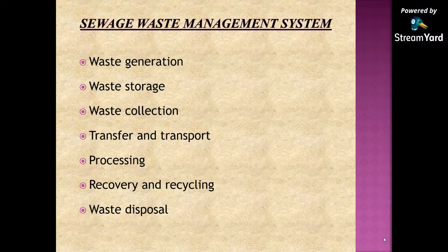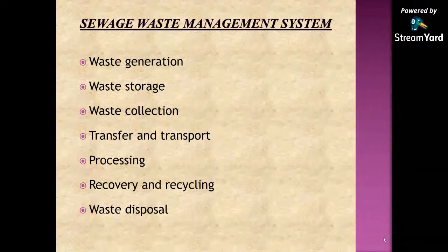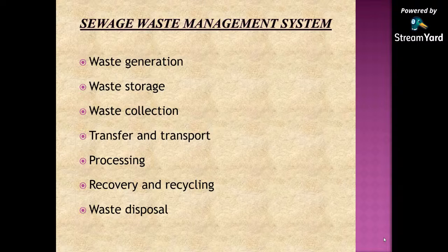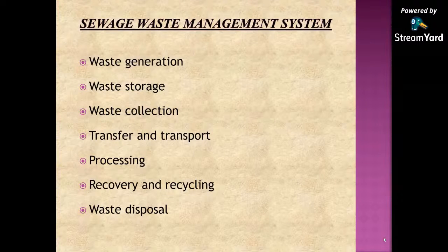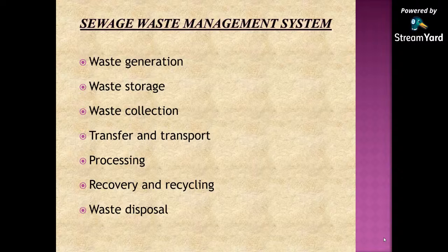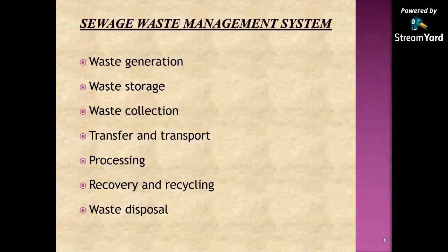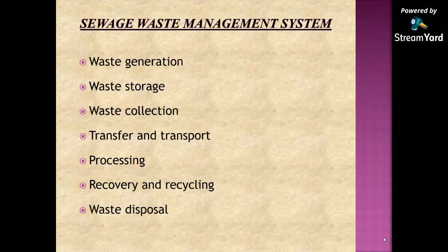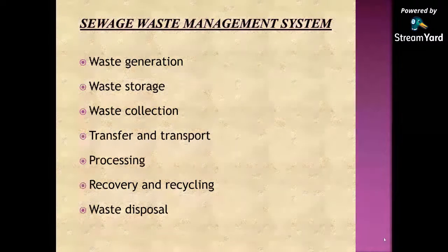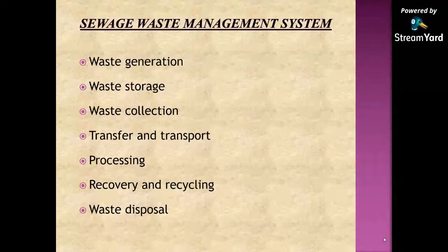Next step of solid waste management is recovery and recycling. This includes various techniques, equipment, and facilities which are used to improve both the efficiency of the disposal system and recovery of usable material and energy. Recovery involves the separation of valuable resources from mixed solid waste delivered at transfer stations or processing plants. It also involves size reduction and density separation by air classifier, magnetic devices for iron, and screens for glass.